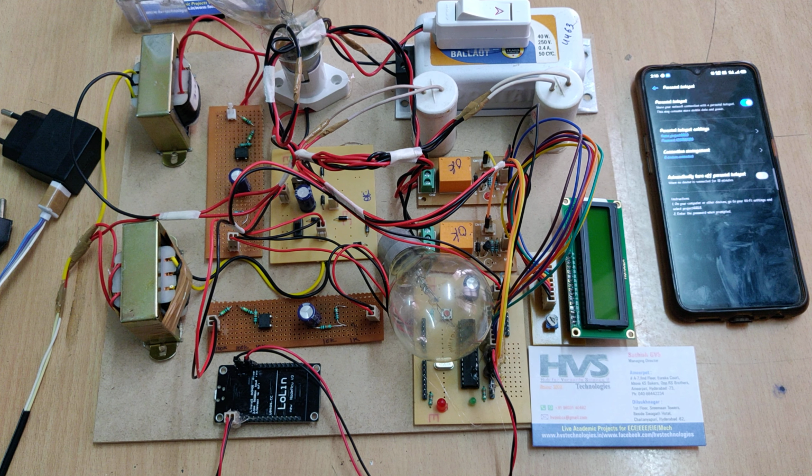on the load directly. Okay, so as we know, if we use an R load, then the phase difference between the current transformer and voltage transformer is 0, and power factor is nothing but cos theta. So theta is 0, it's near to unity power factor. So cos 0 is 1, near to 1.